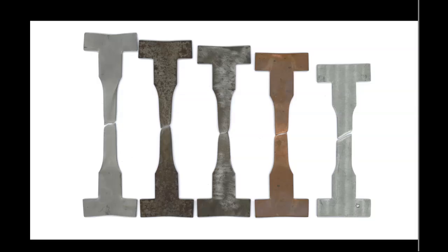As I mentioned in the lecture slides, don't be tricked, as an engineer, that stainless is good. I mean, it's a great steel. For lack of a better word, it's an excellent material. It's corrosion resistant, it's ductile, which means that you can process it. There are some difficulties with welding stainless steel, but there are ways to do it. But in a way, it's a weak material.